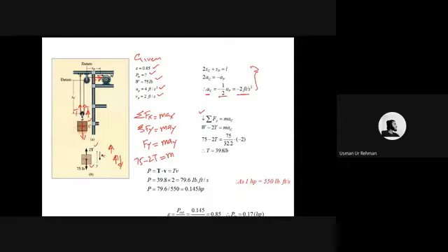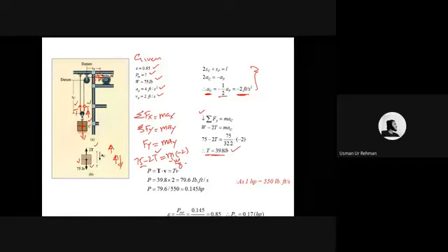And from here we know that acceleration of point C is minus 2 feet per second. So we can put this value over here, minus 2. And how we can find out this m? This is basically equal to W by g. So W is 75, right? And divided by 32.2, so we will get this value. So in this whole equation, there is one unknown, that is T. So this T is now identified. So the tension that we have over here, the tension that we have over here, the tension that we have over here, all of them are identified, right? Is it clear till this point?